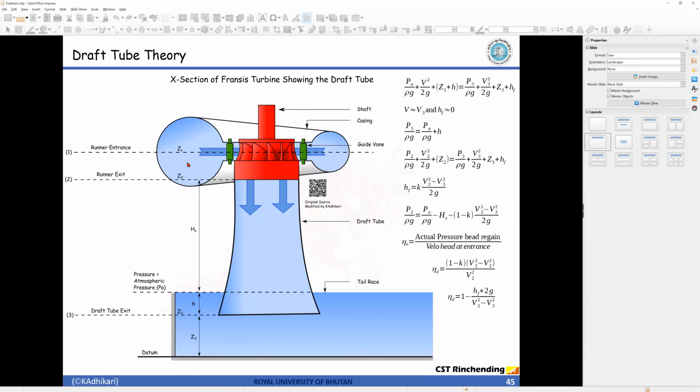Here there is a section of a Francis turbine. There is a turbine here. This is the spiral casing from where water will be flowing. From the section I can make out that water must be going in this direction and coming out in this direction. The cross section here is larger and this side is smaller, meaning water is already getting into the turbine. That's why the quantity of water flowing through is less, and that's why this section is also reduced here.